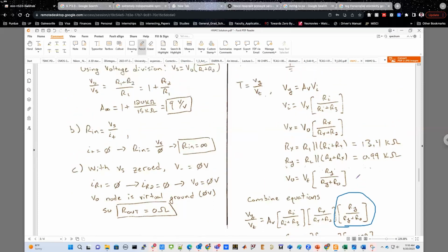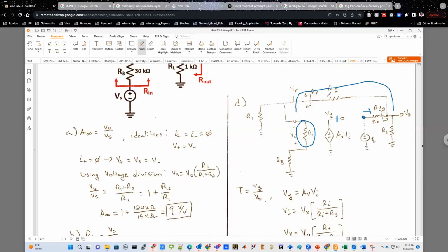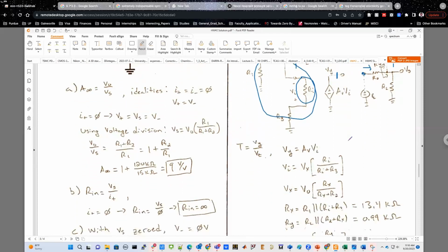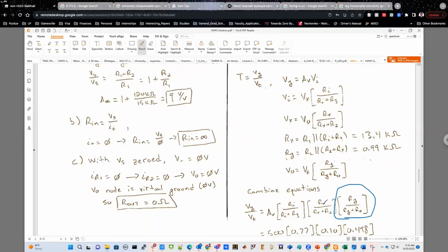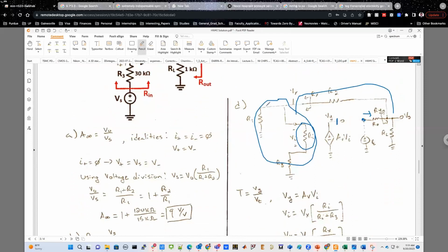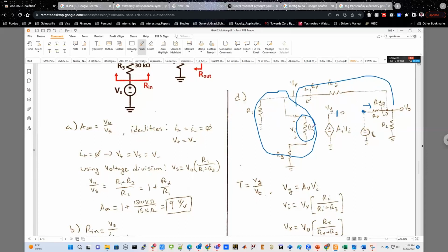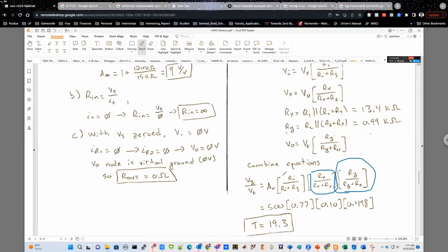Okay. Then you propagate again toward the right-hand side, you see R2, and then again a large network of resistances connected in parallel with R2. What are you interested in? You are eventually interested in that large network of resistances, which is called RX. So in this case, the voltage division ratio becomes RX divided by RX plus R2. And eventually, within RX, you find that there is a parallel resistance R1, and in parallel to that, you have Rin plus R3. Now you are interested in the voltage division between Rin and R3. That's the third voltage division you have, Rin divided by Rin plus R3. And because you are interested in the voltage across Rin, it is in the numerator. I hope that answers your question.